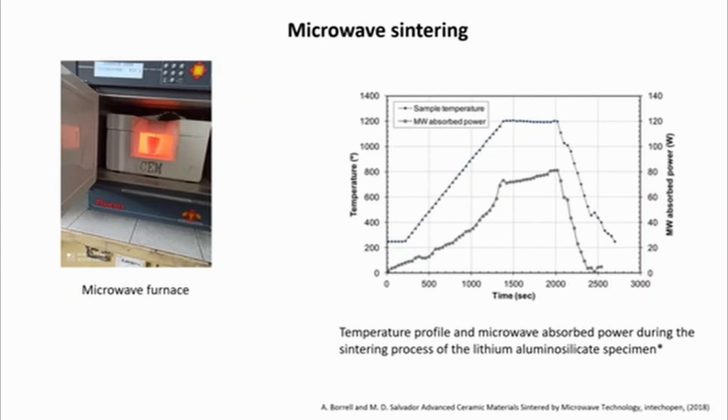The most important advantages of microwave sintering against conventional sintering methods are listed as follows: shorter sintering time and lower energy consumption. Higher heating rates can be used. Material with a fine nanometric microstructure, a high degree of densification and enhanced mechanical properties may be obtained due to the densification mechanism involved. It is also flexible due to the possibility of processing near net-shaped materials.